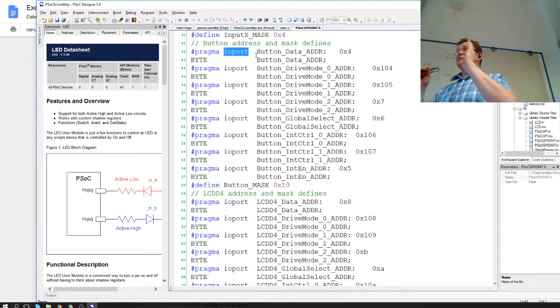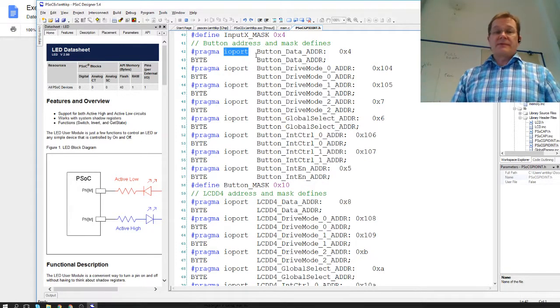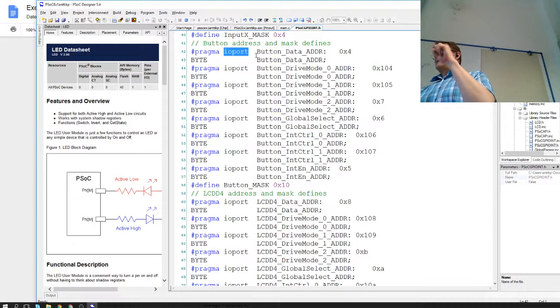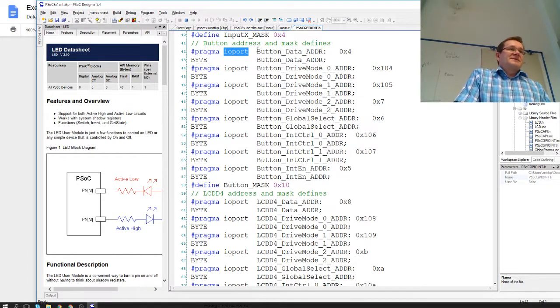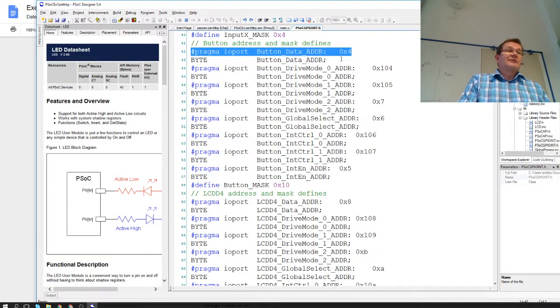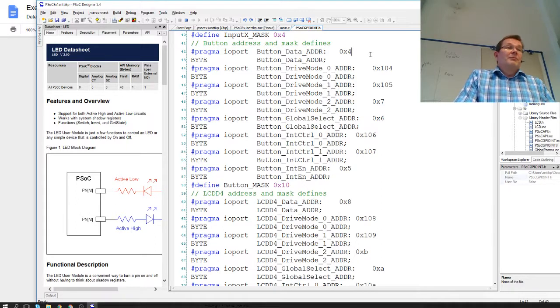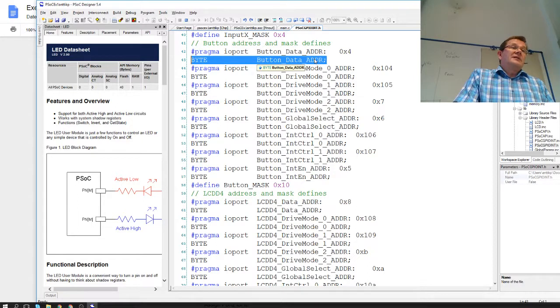So the I/O port is on a different address space, and that's the way to tell the compiler to make all of those accesses using the assembly code that relates to that address space. Nothing more than that, and you don't need to worry about it since this is done already by the compiler. You just need to know that you can read that data from this variable.